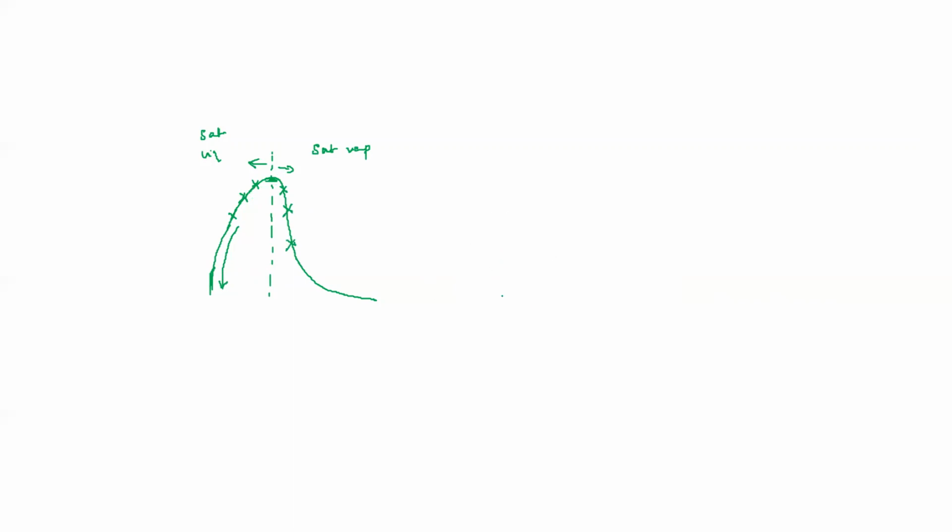So if you take the saturation curve and mark a point, this is my peak. You mark a point here, let's call it A, and at A the temperature is, let's say, 220 degrees Celsius. From here, if you draw a straight line, then over here you'll find, let's call it B. The temperature is going to be the same, and B is going to be saturated vapor.